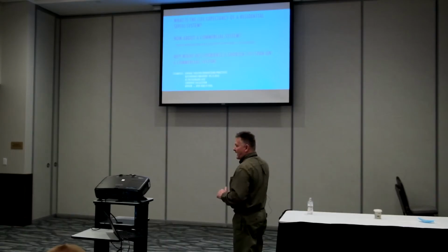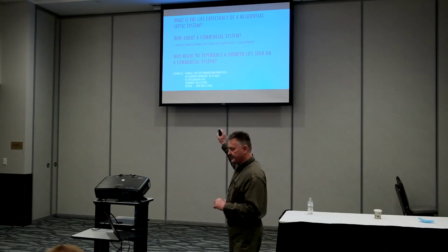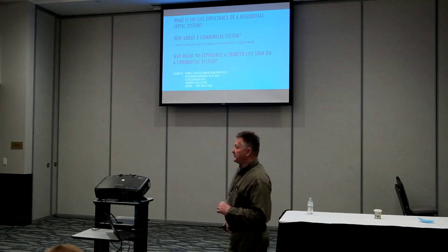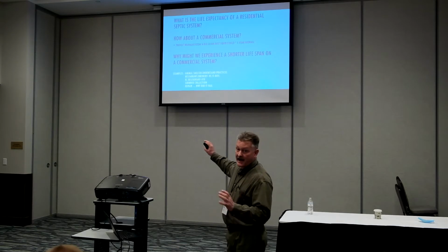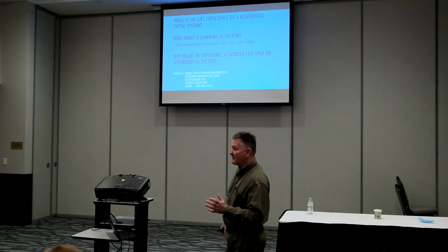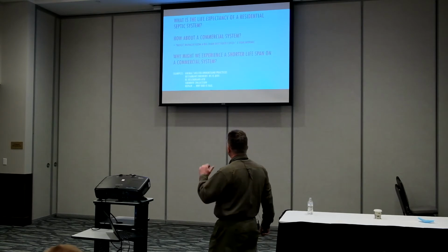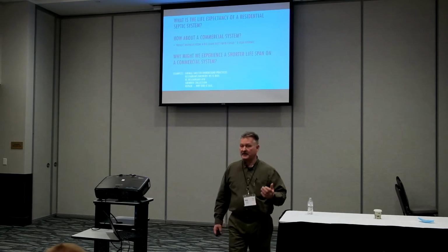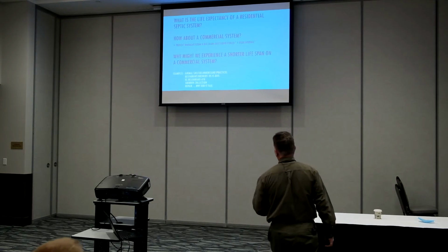And because there's a lot of variables that we often don't integrate into our design. Back in my early days, when I first hired on, I did a number of projects with fast food restaurants, McDonald's, setting up some treatment systems. Talking to one of the corporate McDonald's project managers, he indicated that on average across the country, their restaurants see an average life of the drain field of about 5 years. Because of the number of variables that we'll discuss here, oftentimes we can have a shortened life in that system. We're not going to have the life that we would expect out of a residential system.